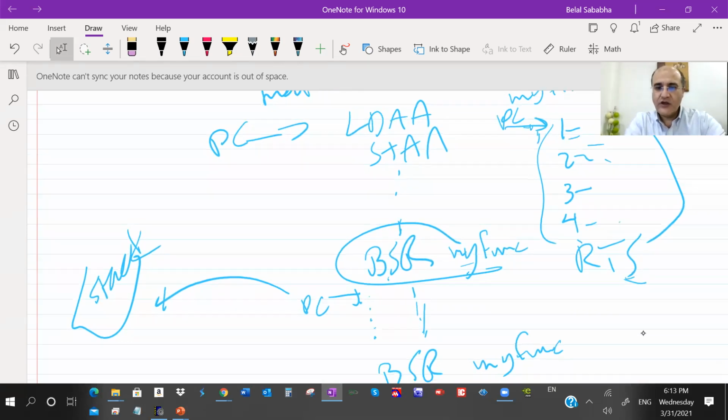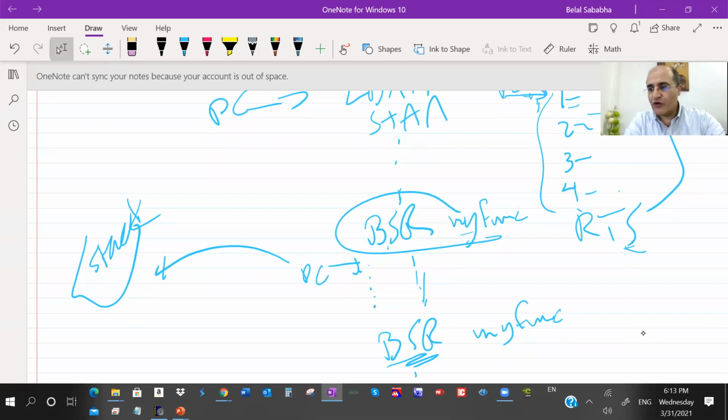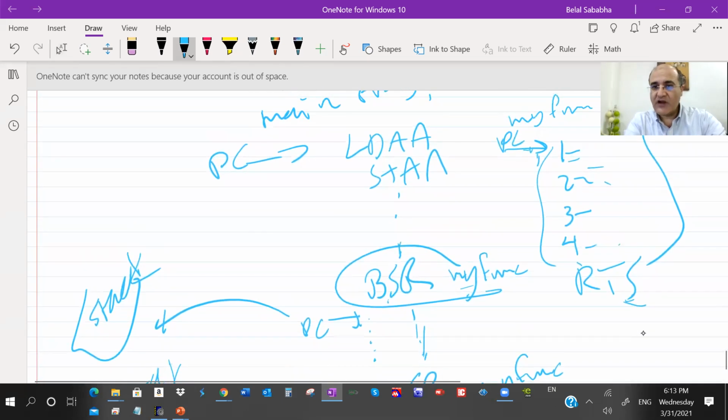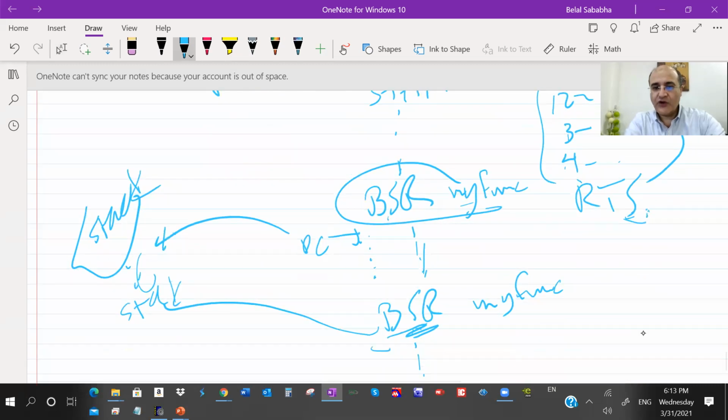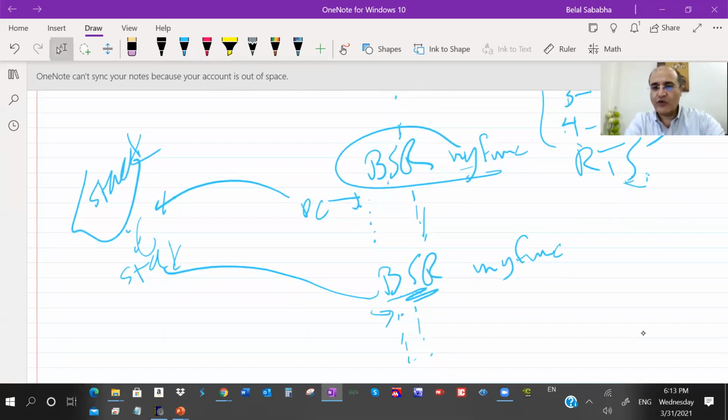You continue. You call it again. You call the function, or the branch to the subroutine. This will save the program counter in the stack. Make the program counter point to the first instruction in the subroutine, and execute them. When you're done, you go to the stack, get back the value, put it in the program counter, and continue at the point where you were before calling the subroutine. So it's a different concept than a macro.